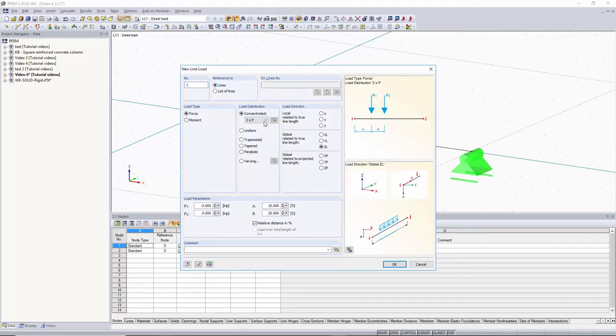Now let's say we wanted those same options, but we didn't want pairs, we just wanted a single point load. Well, we have the option for 2 times a point load, and now we can do 2 separate point loads. Let's make this -5 kips. We can make the second one -3. And we have the option to set these 2 point loads 25% away from the start for A, and then the distance between those 2 point loads we can set to 30%.